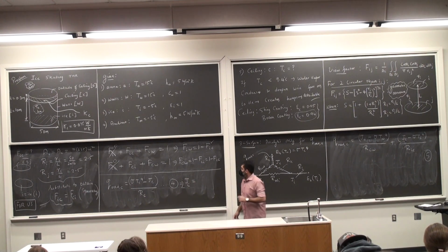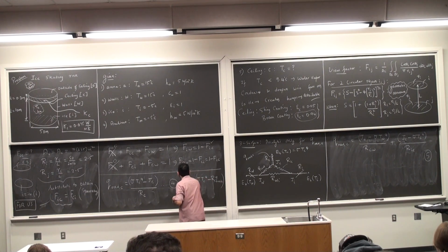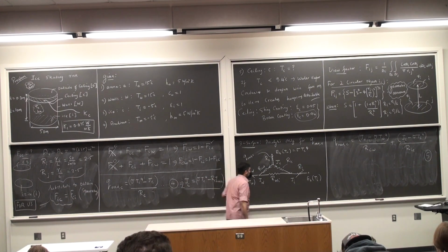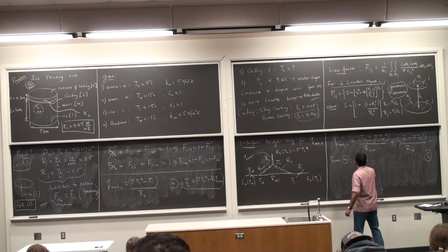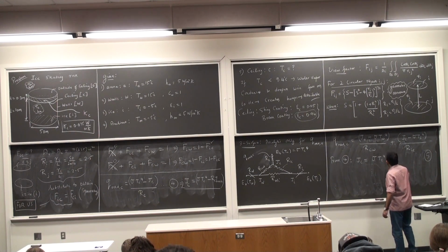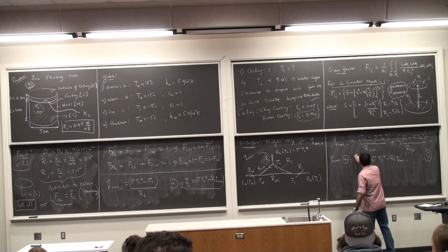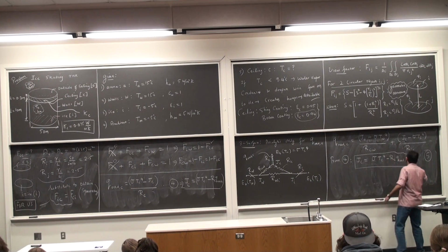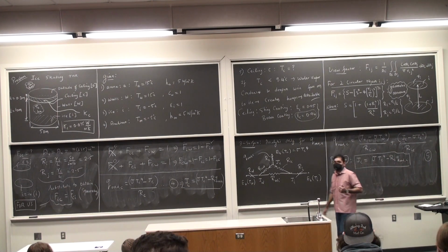Jc is the following. It is sigma Tc to the power 4 minus Rc Q radiation C. I'll rewrite it here. So from equation 4, Jc is sigma Tc to the power 4 minus Rc Q radiation C. Does this make sense to everybody? I'm just rearranging it and writing Jc.